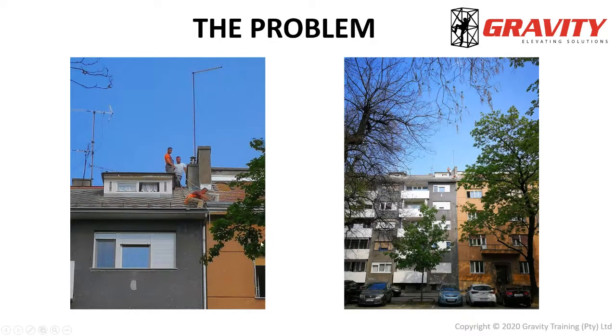If this guy is properly trained, he would understand the risks involved in rooftop work, being especially one of the more dangerous aspects of work at height, as we've covered in the low-level heights masterclass, which you can go back and look at on YouTube. This guy is unaware of the risks, thinks he's safe, and therefore does not take the correct precautions in terms of his footrest system and, by extension, his anchor system.